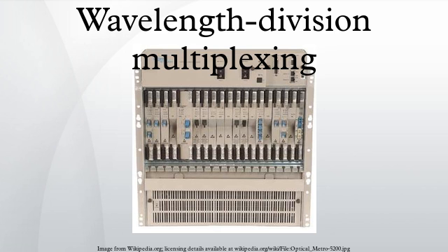At the remote site, the terminal demultiplexer consisting of an optical demultiplexer and one or more wavelength converting transponders separates the multi-wavelength optical signal back into individual data signals and outputs them on separate fibers for client layer systems.